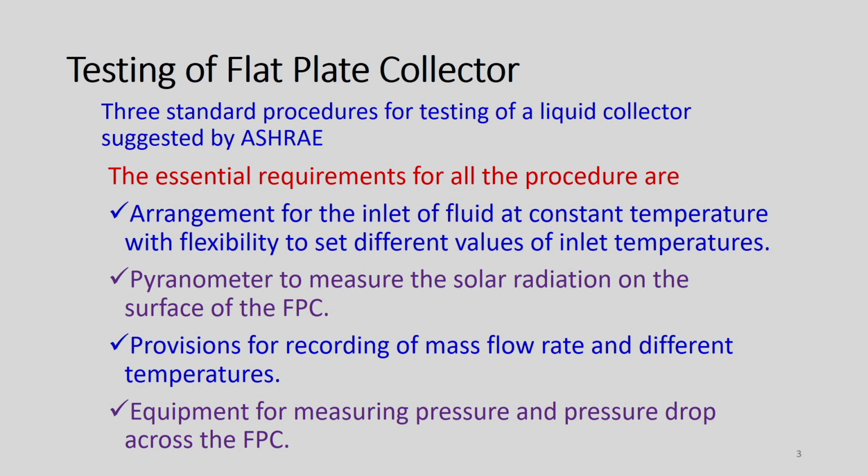The essential requirements for all the procedures are: number one, arrangement for the inlet of fluid at constant temperature with flexibility to set different values of the inlet temperatures; a pyranometer to measure the solar radiation on the surface of the flat plate collector; provisions for recording of mass flow rate and different temperatures; and equipment for measuring pressure and pressure loss across the LFPC.